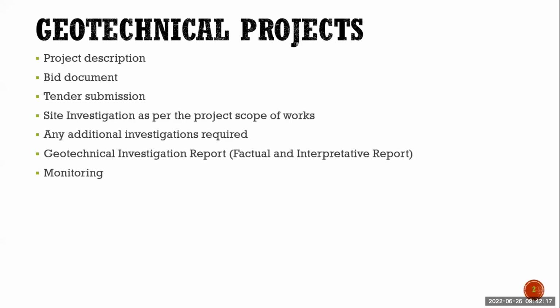Then the engineer will say, in order to construct, we have to know the foundation material. To know the soil properties of that particular land, we need to proceed with geotechnical investigation. Just by seeing, we cannot determine the soil properties. We have to do some testing. We have to collect samples and analyze them, and do some tests on the site itself.